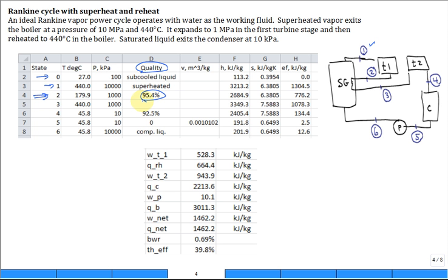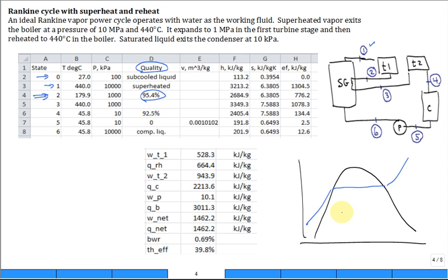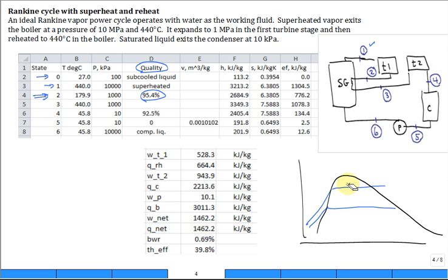So that state 2 came into the dome on our temperature entropy diagram. If we sketched it and tried to be accurate, you'd put a dome like this. You put the high pressure line like this, and an intermediate pressure line, and I'm not doing that so good. I need to flatten that dome out some more, like that. Put that like this, then like this, then like this. And so if we come out here, we expand, we get 95% quality at state 2.